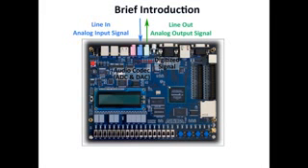Once you have completed this lab, you should be able to create the basic framework for real-time digital signal processing using Simulink, Altera DSP Builder, Courseware and DE2 board. Understand the effect of quantization in ADC and DAC. In this experiment, we will build an audio loopback project in Courseware using the schematic entry method. By using the template folder, which consists of the DE2 audio codec modules, rename the template.bdf into loopback.bdf.